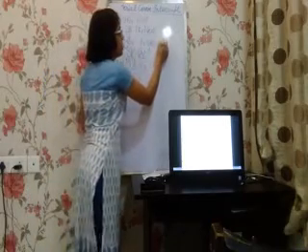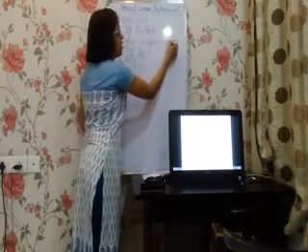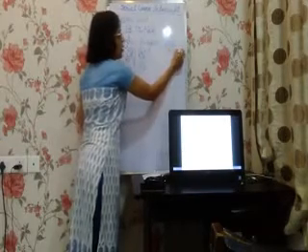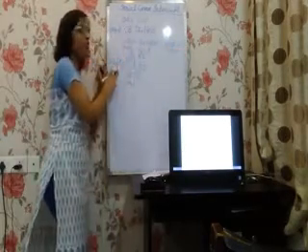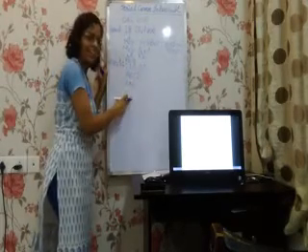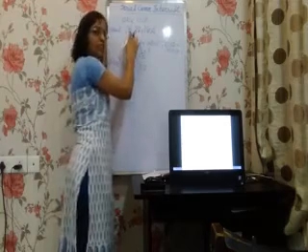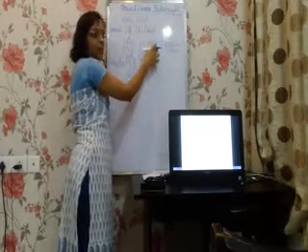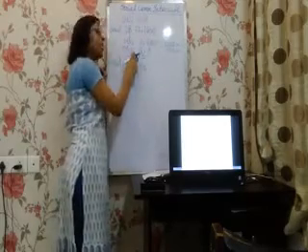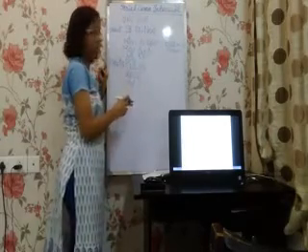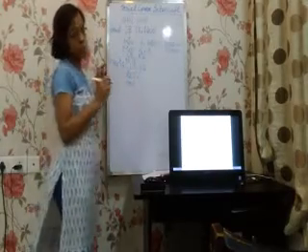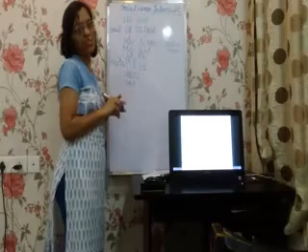This means 8051 as receiver. Okay, if TI is 1, 8051 is acting as a transmitter. TI 1, clear TI, RETI, end. If not, 8051 is working as a receiver. Put the received value from SBUF into A, from A to port 2, save it at a safe place. Clear the RI flag and return. Okay, this is how you are going to do serial communication programming for serial communication interrupt.